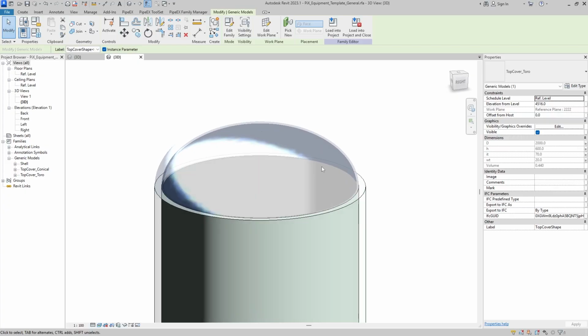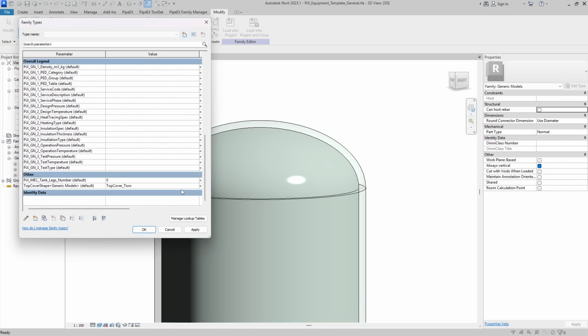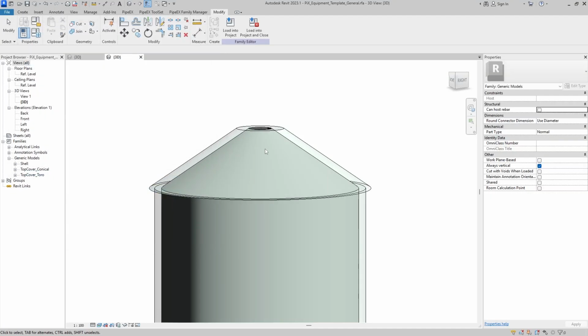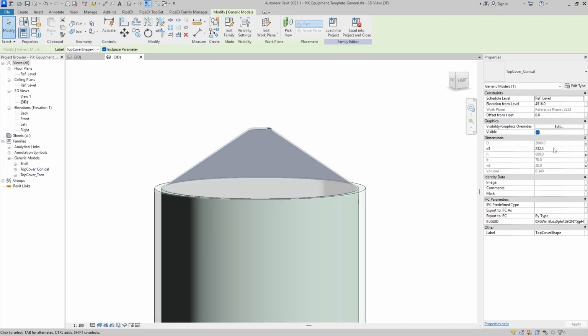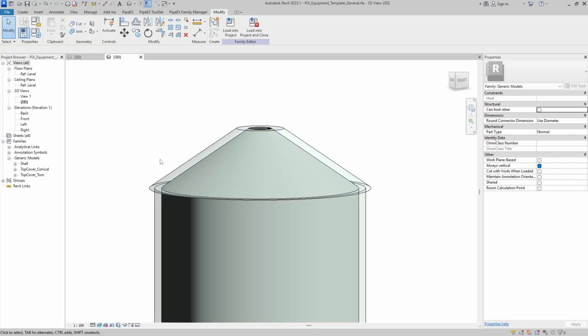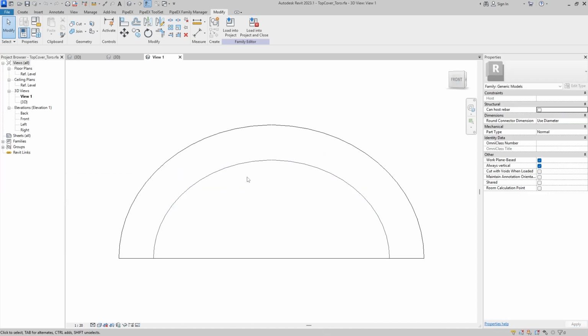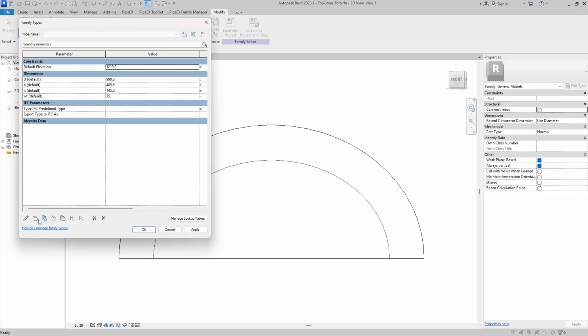It was replaced, and technically nothing went wrong, but now when I move it back, this parameter will not be assigned anymore. So even if in your case this parameter will always be equal to 0, you still need to mention it, and you need to bind it to the desired parameter. And this is what I'm going to do now. I will click on edit over here, and I will just define d1.